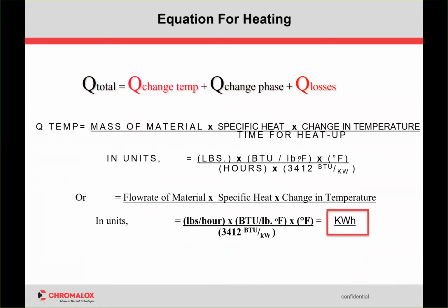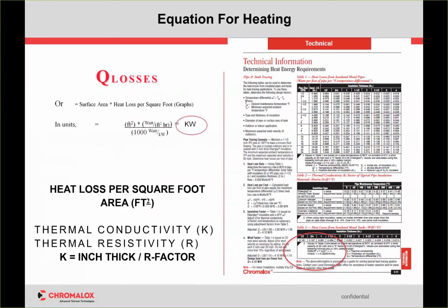But always remember it's kilowatt hours. The rating is the H gets left off. It's left off in pretty much all of our catalog products. But that is the thermal input in an hour. And when you have heat up times, maybe you have longer to heat something up, less time to heat something up, that all becomes a factor, and it's just important to remember.